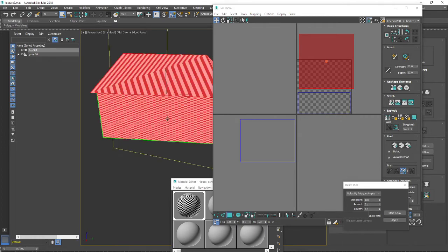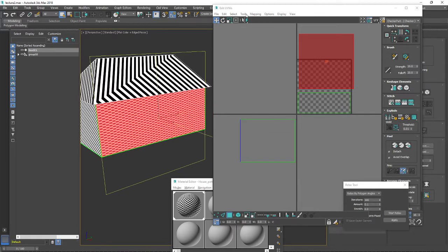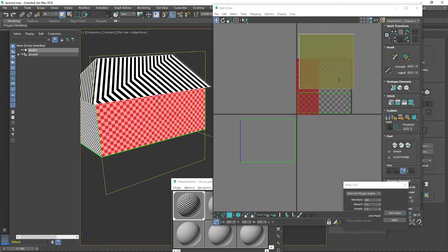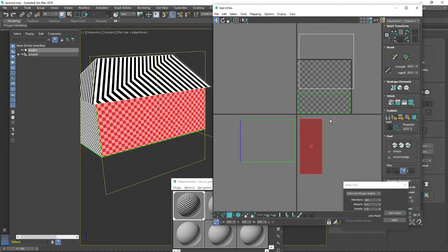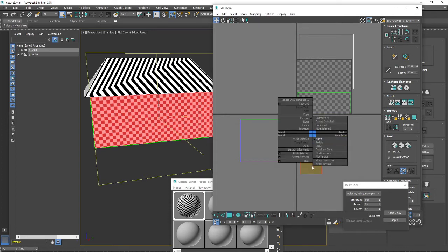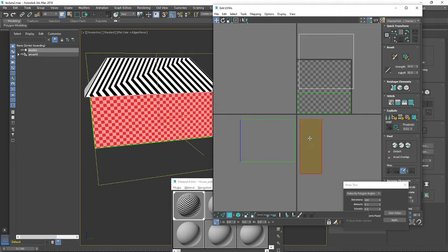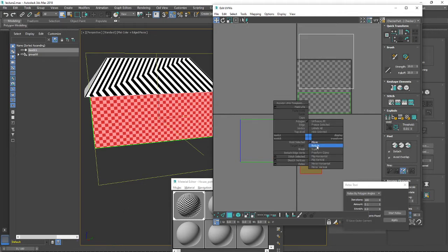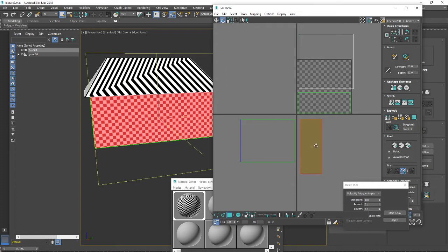Once again, let's select another wall, go to the flatten mapping and press OK here. You can see our wall right now is rotated. To rotate it, we will use the quick transform tool from here, or you can always press the right mouse button on the polygon and choose rotate, but I expect you guys to use this rotation because it rotates by 90 degrees like that.